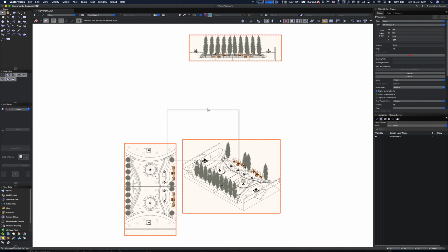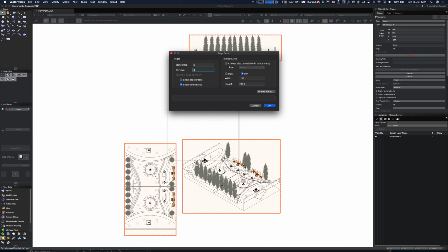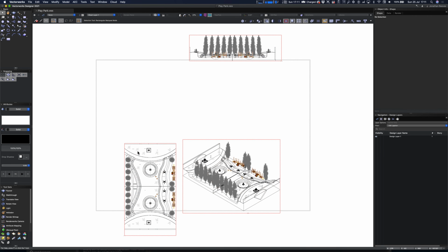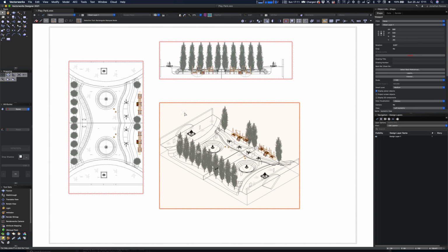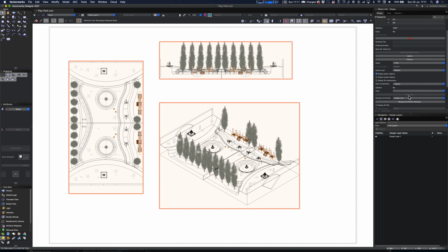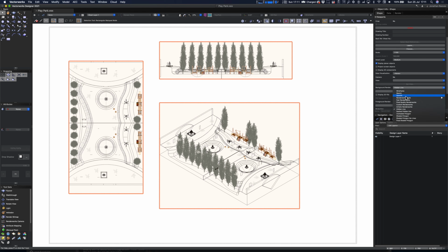So really, once you've got your model, to create the drawings from that model is very, very fast via the viewport system. Creating multiple viewports is something that's quite a fun thing to do. The other thing to do is just duplicate the viewports and change the view as well. Excellent. Okay, so what we'll do, we'll select all of them. Let's change them all to OpenGL.